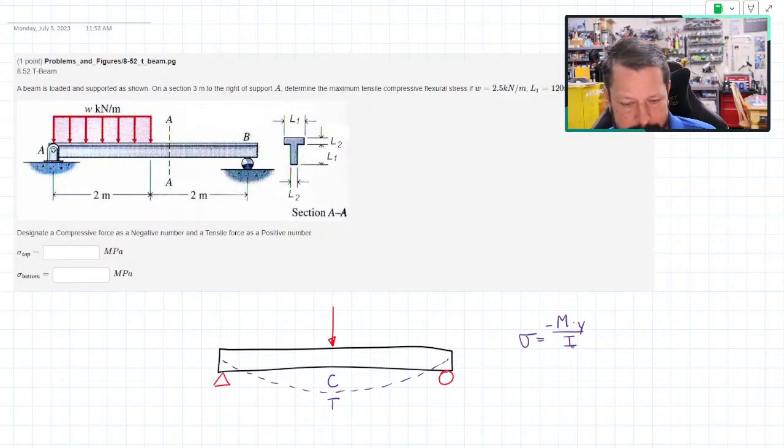While we're on these little asides, I've been saying that when we draw the internal bending moment and the internal shear force, there were particular directions we had to draw the arrows. We'll actually do some of that later in this problem, but most of the time, when I tell you you're writing an equation, summation of moments about some point equals 0, you can choose clockwise or counterclockwise to be positive for that equation.